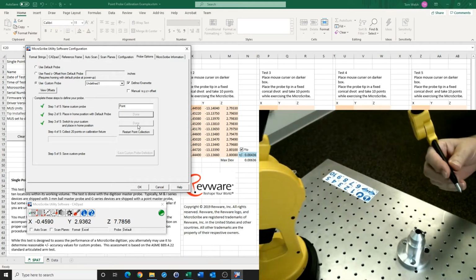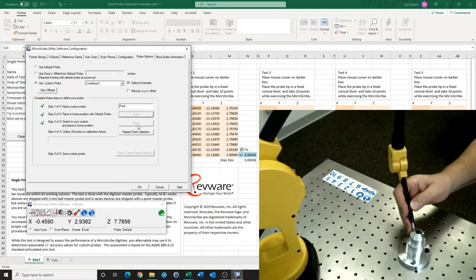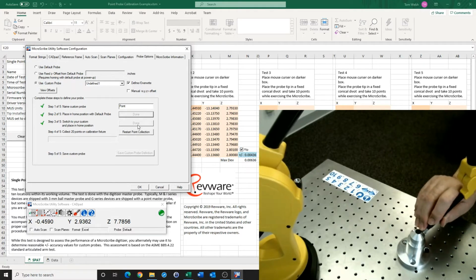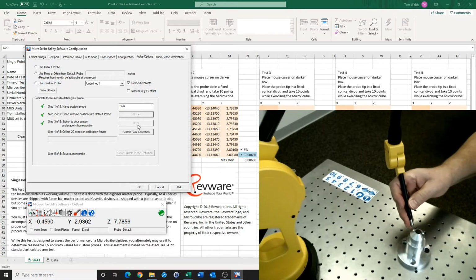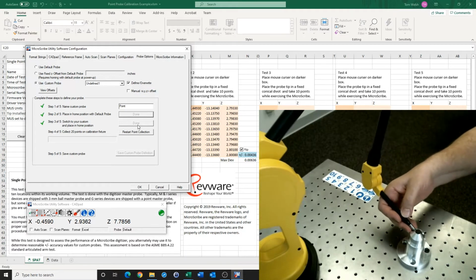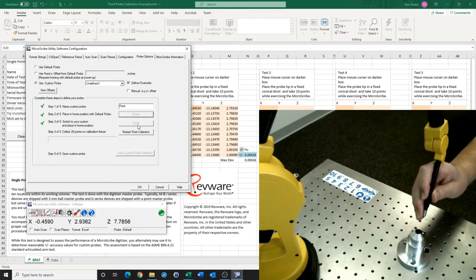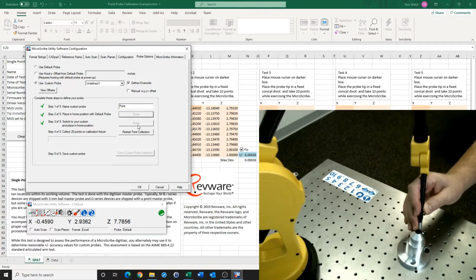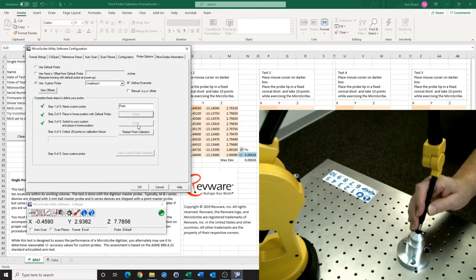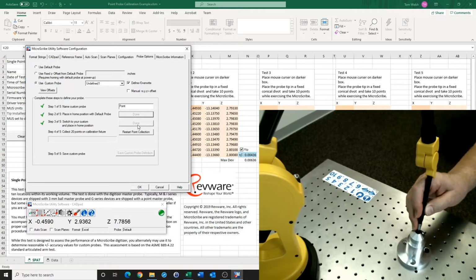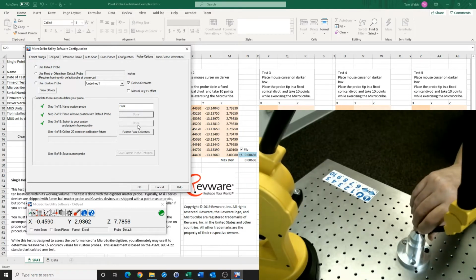for it. Now, the thing about a point probe is that we can't use any of the divots on our calibration fixture. What happens is as we're moving the probe around, we'll literally be pulling its point up out of the divot, and that means that we're not getting data around a specific point. So you'll want to use the top of your calibration fixture, which is admittedly kind of slick. You're going to have to practice to make sure that you can actually hold that tip in one place and not let it slide while you're doing the process of taking 20 points.